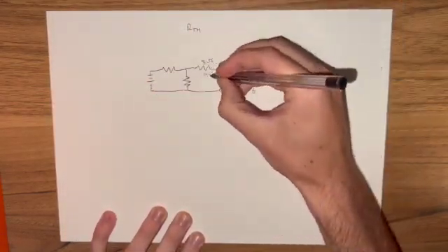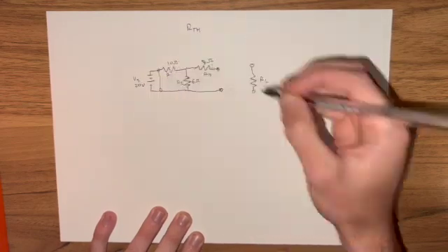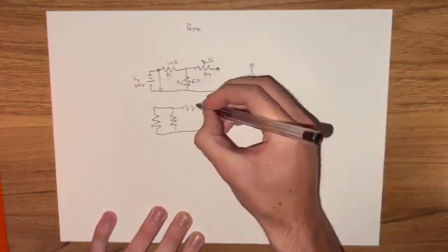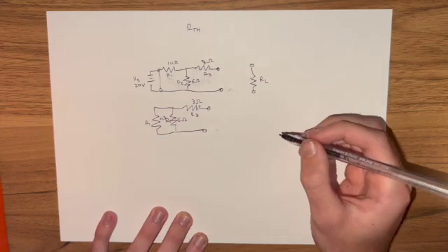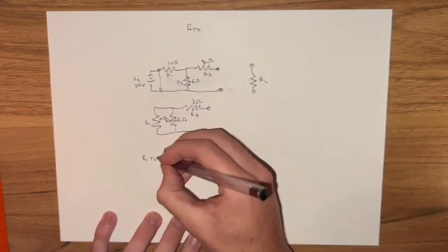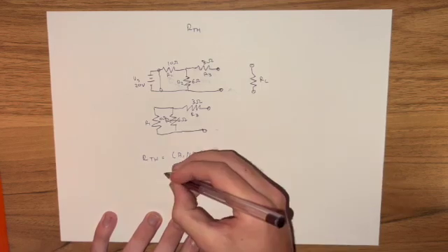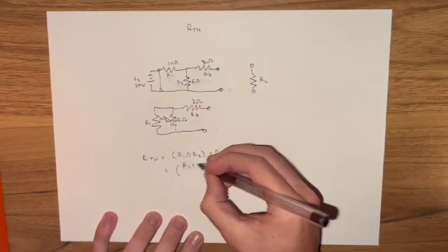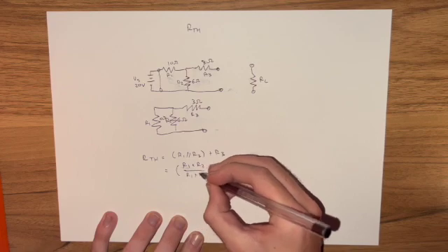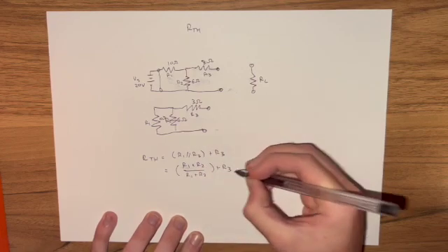To do this, we need to remove the voltage supply by shorting the circuit across it. Doing this, we can redraw the circuit to show R1 in parallel with R2, calculating the Thevenin resistance where the load resistor has been removed. To calculate the Thevenin resistance, we can find the resistance of R1 and R2 in parallel, and add this to R3 as they are in series.